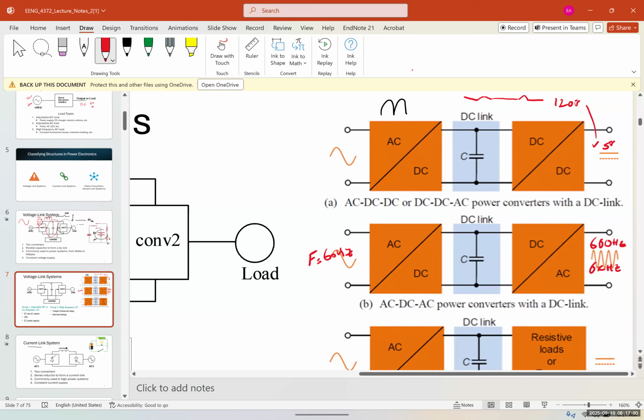Okay, if we want to change the voltage, we will simply add a transformer at the end or at the beginning, and we can regulate. And an auto transformer, I'll explain later what that is. You can adjust the voltage as well, but the frequency is controlled with the switching cycle, what we call, and that's through the control system. And finally, we have the AC to DC and DC to AC, and these are used again for different applications, for example, battery storage systems, and to be able to control some power loads, especially resistive loads and energy sources as well.